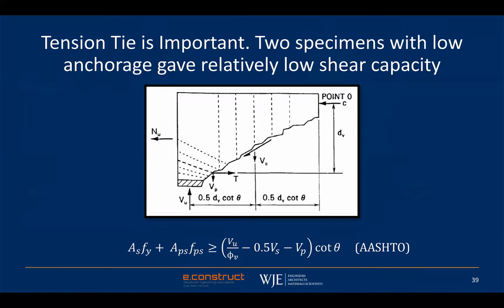One thing we have to emphasize to you as you go through your design is to make sure that you have enough anchorage of the flexural reinforcement into the end zone. Because if you don't have that anchorage, you don't develop the arching effect and you don't develop the capacities. And that's nothing new here. That's the same thing as we would do with conventional concrete.